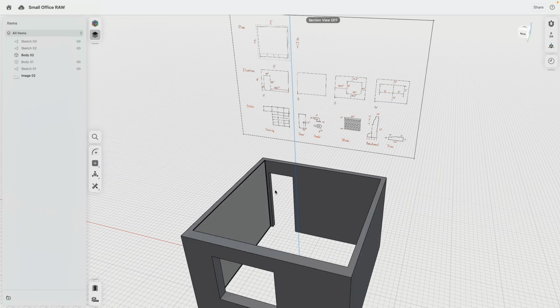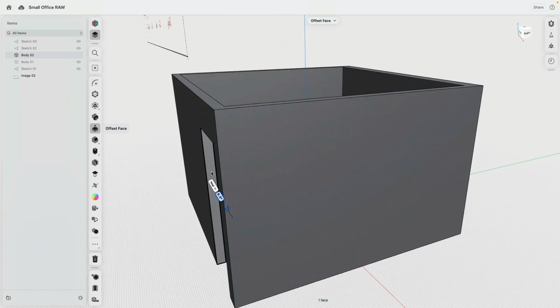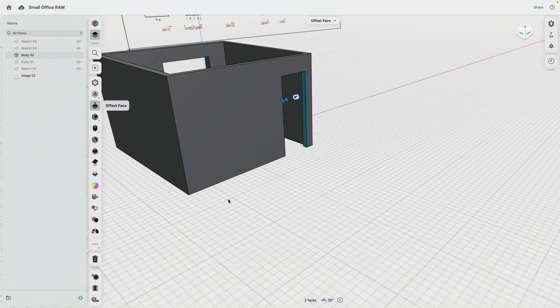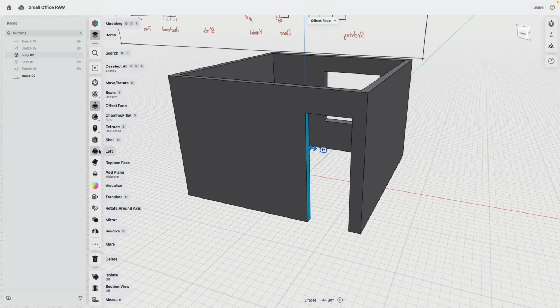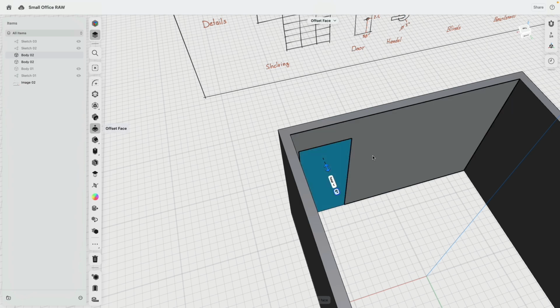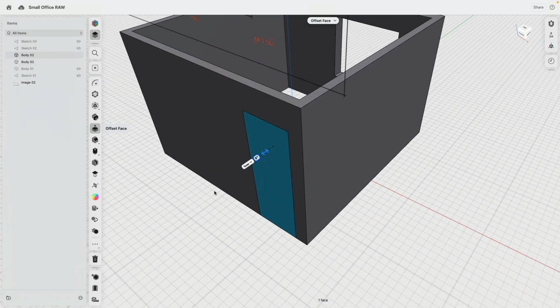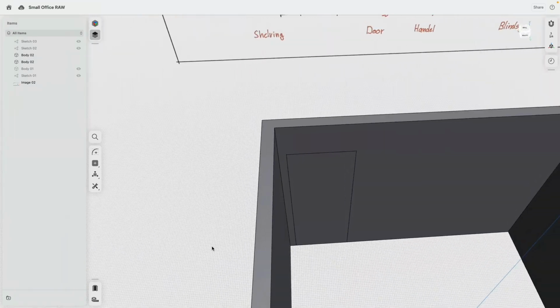Beautiful. Cool. How do we do now a door? Well, we have everything for it. We don't need to sketch the door. I can simply select these 2 elements and then loft it. The door is kind of flush with the wall there, and that is a 5-inch door. That's really thick. Normally it's like 1.75. Let's make it 2 inches. The door is also perfectly flush. Now we can rotate this one out, but for a quick demonstration, this is sufficient.